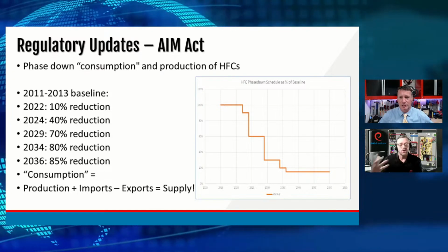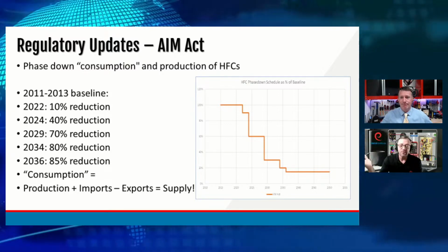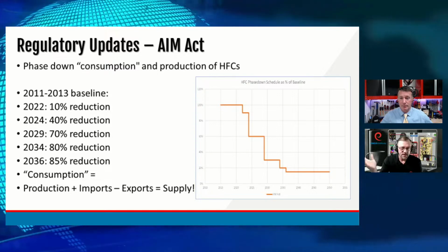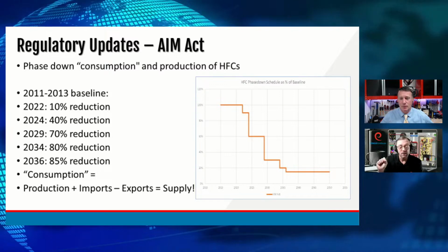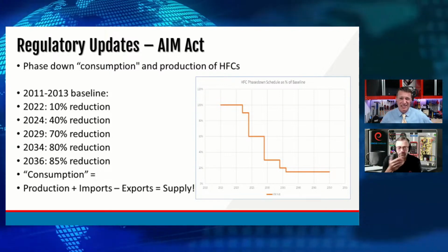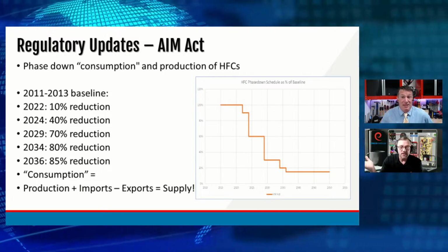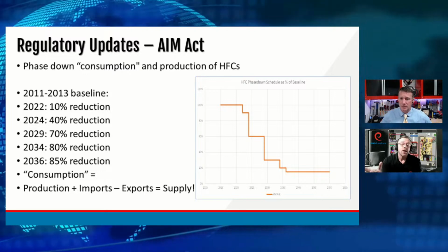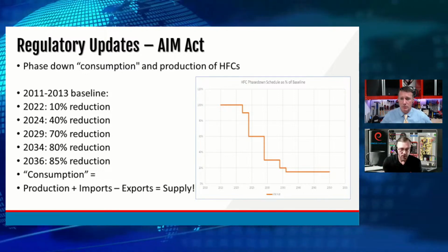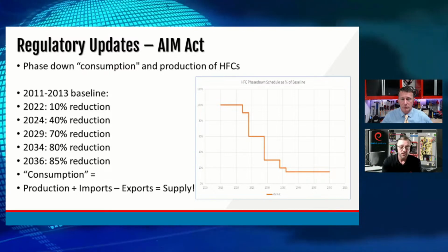Correct, absolutely. Some manufacturers are just going to look at the high ones. I don't want to point fingers, but let's say 4048, 3920. That's a big chunk, a big withdrawal from my allotment. What if it's an HFO at like 7? Right. Or R32 at 676. Exactly. So 3.5, 3.25. This is going to affect some refrigerants more than others, based on the manufacturer and the GWP of the refrigerant.